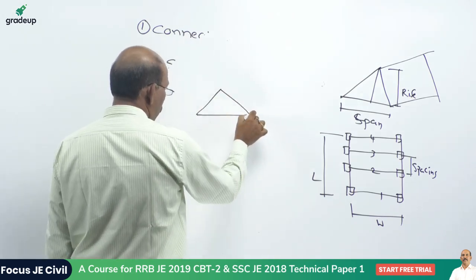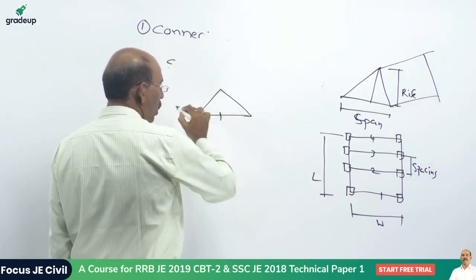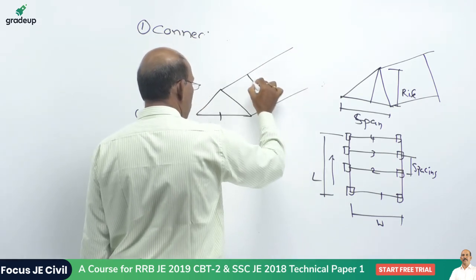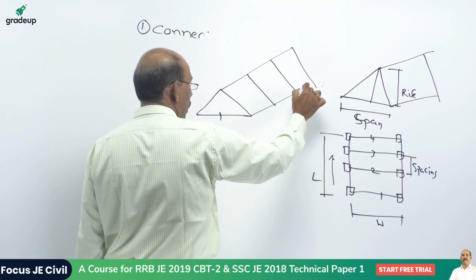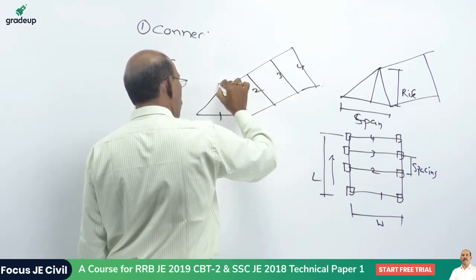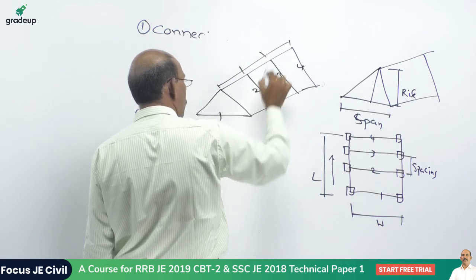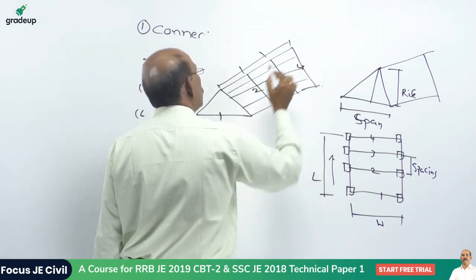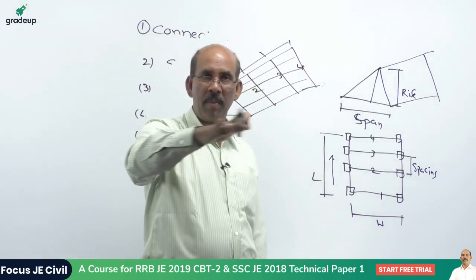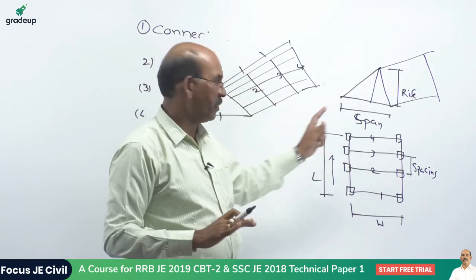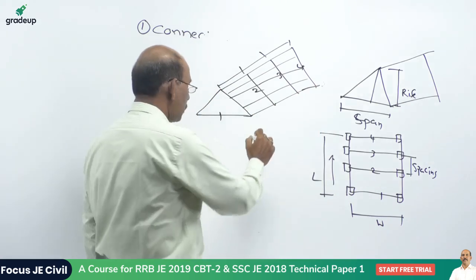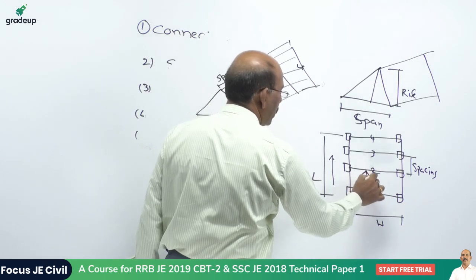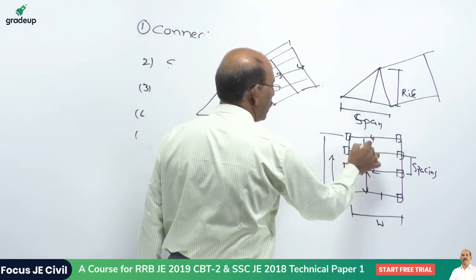So this is the first truss here, number 1. So coming in this direction, I have the number of trusses. So this is truss 2, truss 3, truss 4. So like this 1, 2, 3. So I made this spacing between one to the other by means of connections, the purlins. So this particular one, the roofing material and as well as the length and as well as the spacing between each truss, this is the spacing. So this is the spacing between first to the second and second to the third and third to the fourth.